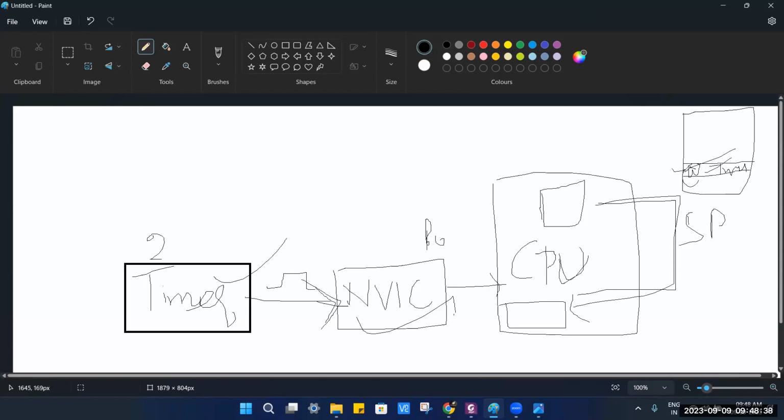because it got the data. Then it will load it to the program counter, because this will be having the base address of the starting address of the timer handler, and the timer handler would get executed. Once it is executed, it will pop the stack back and start executing what it was doing. Depends. If it gets another interrupt, it will do something called tail chaining. In that case, it will not do the push pop operations. It will continue execution in the privileged mode itself, that is the supervisor mode. In case of ARM, we have thread mode and handler mode.